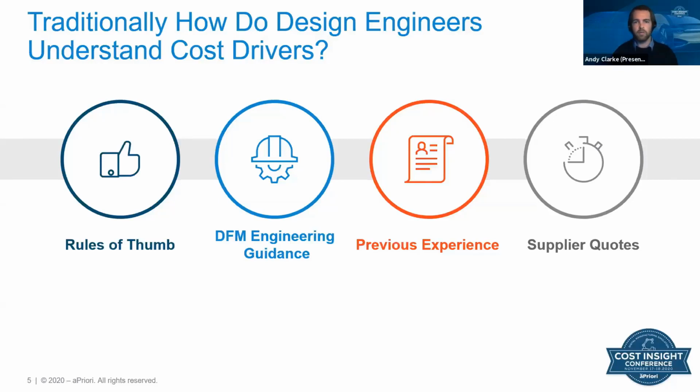Typically, most design approaches, regardless of which process you're looking at, will have a certain degree of rules of thumb, a certain way of approaching designing a part for a particular commodity. If we think about a universal one, you typically always want to design a product with as few parts as possible. It's less inventory to keep, it's less parts to keep track of, it's less development to do.